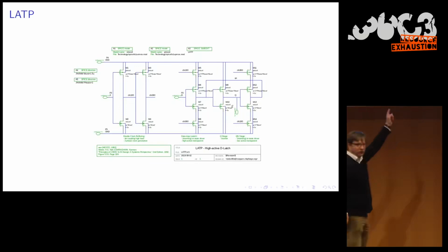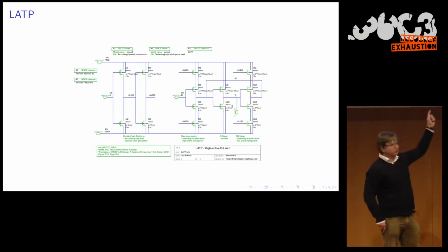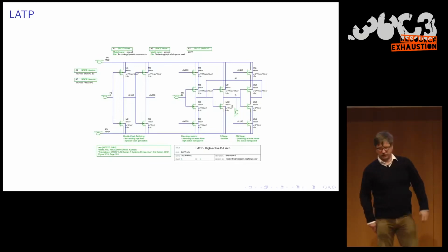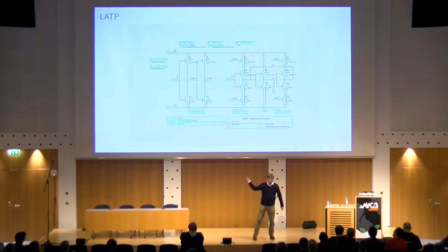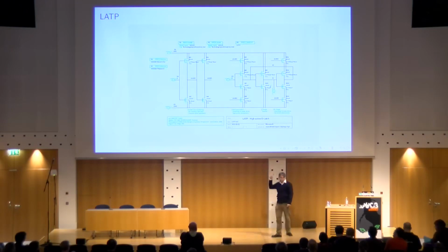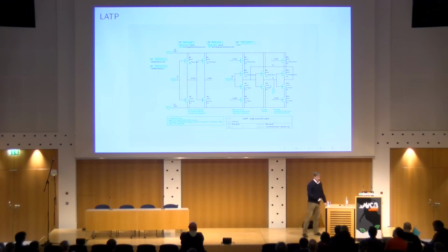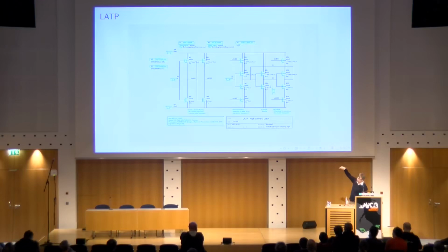If we have a look at this stage up there, that's an inverter. It can be three-state. This means when the clock is in a non-ideal state for the lower and higher transistors, then it doesn't matter what's in the D input. It doesn't let it through, it doesn't invert. It can drive when the clock is correct.